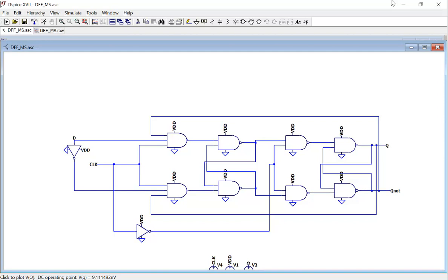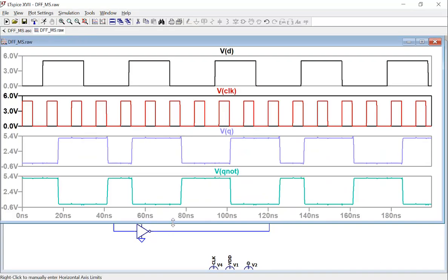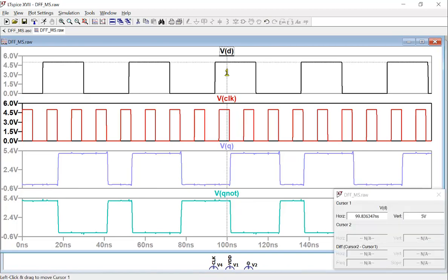It's rising edge triggered, actually. So now let's take a look at the graph, see if it's exactly rising edge triggered, right? So here's D, here's clock. So if you just look at this period, the rising edge samples a 0 from D, right? The rising edge samples a D. But the falling edge sends a 1 to Q. Does that make sense?